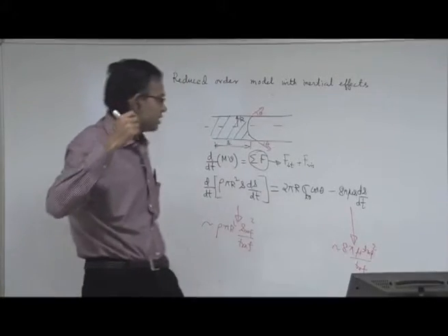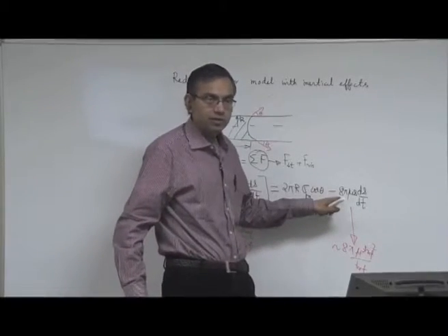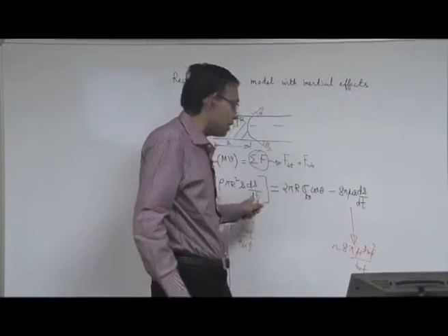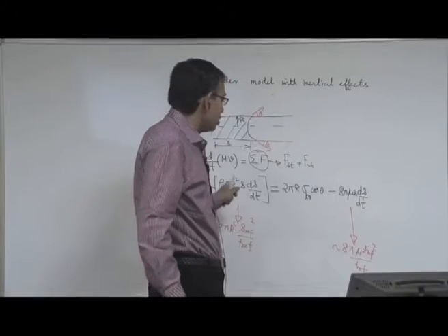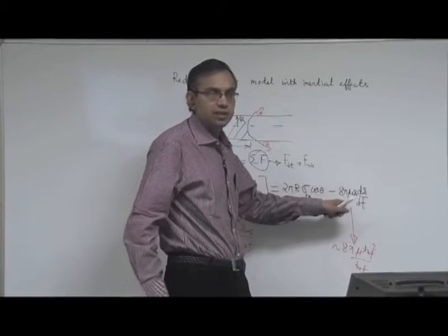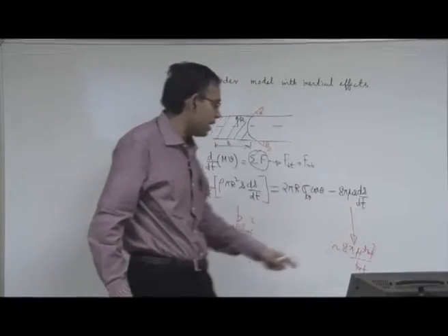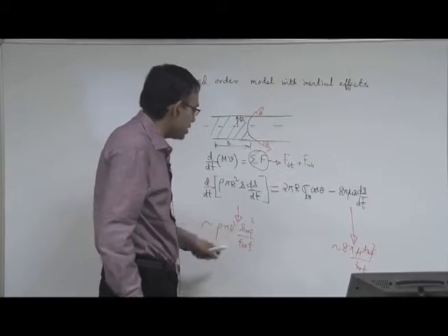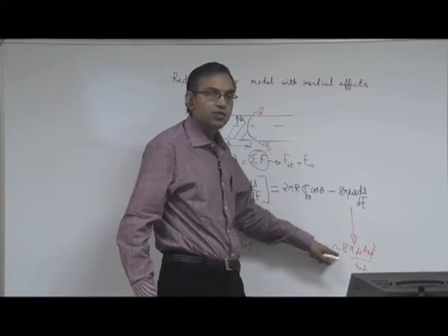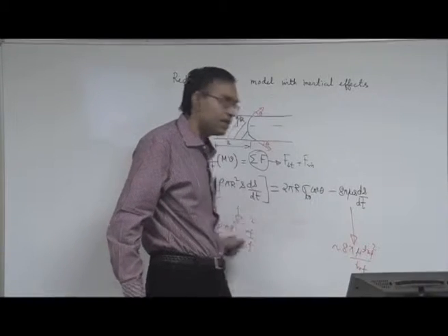So, that means the viscous force will also be important, and when inertial effects are important, then only this term is important. Therefore, the inertial term also has to be comparable with either of these in a competing environment. That is why, when we are trying to establish a proper time scale of the problem, we can equate this with this to get the time scale; the length scale gets cancelled out.